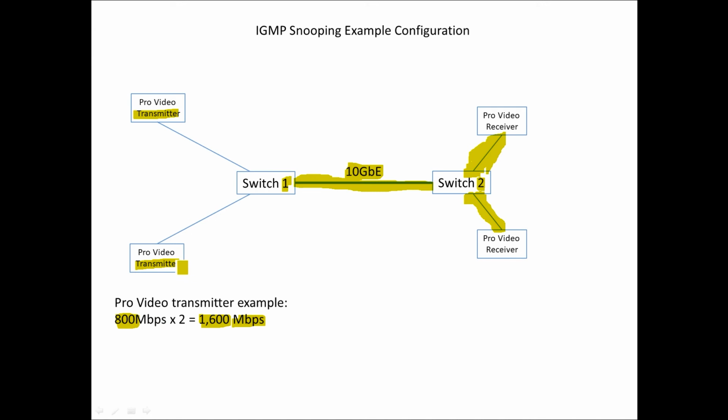The other thing I should also clarify is there are different levels or different product categories as far as the video transmitter receiver solutions from the different respective manufacturers. So there are higher end video transmitters, more premium versions, if you will, higher cost, that do offer flexibility, such as you can go from constant bit rate to variable bit rate. You can also adjust the megabits per second. So that's good. So you could potentially squeeze this number down, this 800 megabits, to a lower number, again, depending on resolution, frames per second, color bit depth, compression algorithm, and so on and so forth.